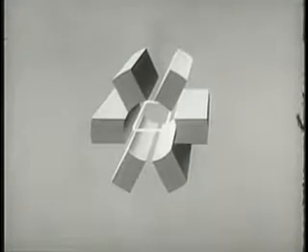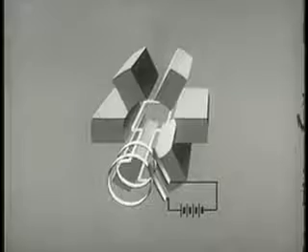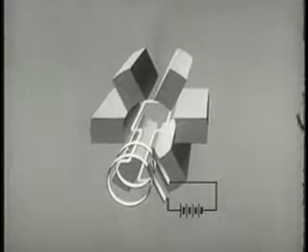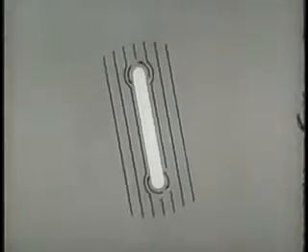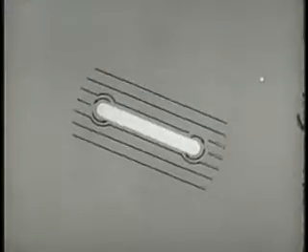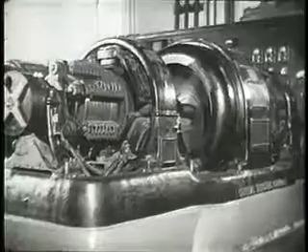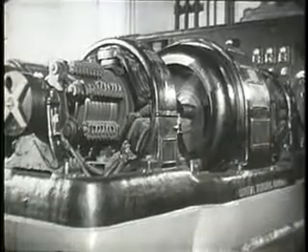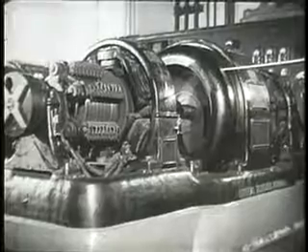In the synchronous motor, however, a different situation exists. Here, a multi-phase source of AC is applied to the stator windings, producing a rotating field, and a separate DC voltage is applied to the rotor windings, producing an independent magnetic field. There is no need for relative motion here. The synchronous motor is so designed that the rotor and the field rotate at the same speed. This is of importance when synchronous motors are used to drive equipment requiring this characteristic.